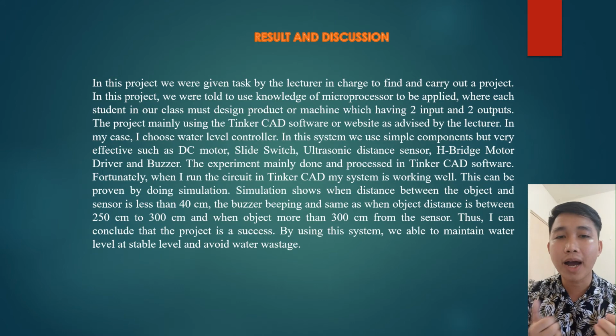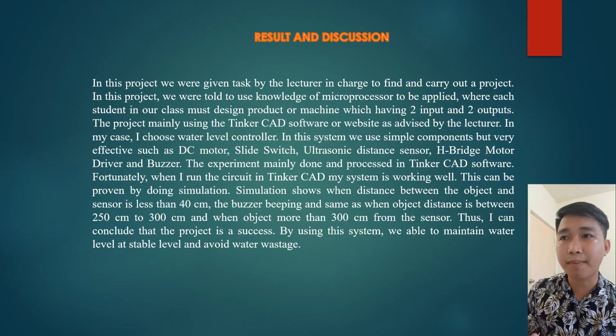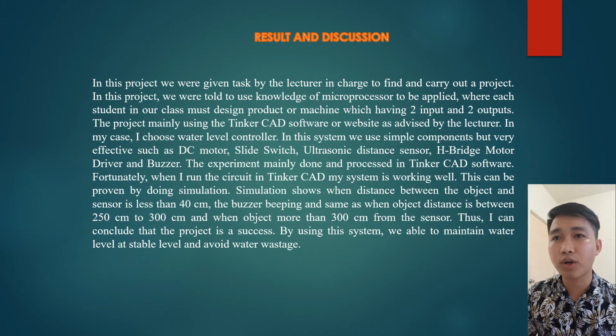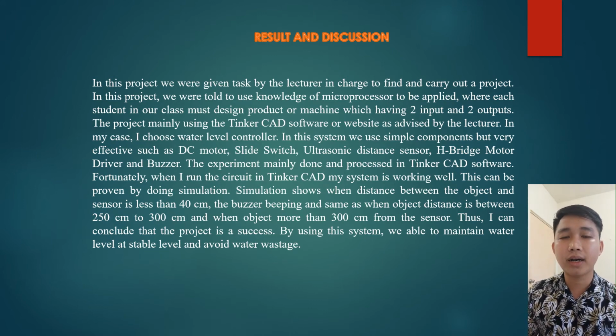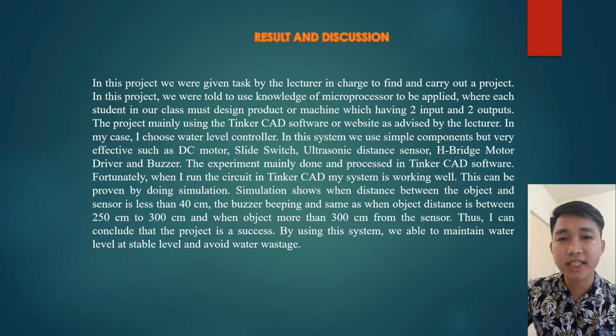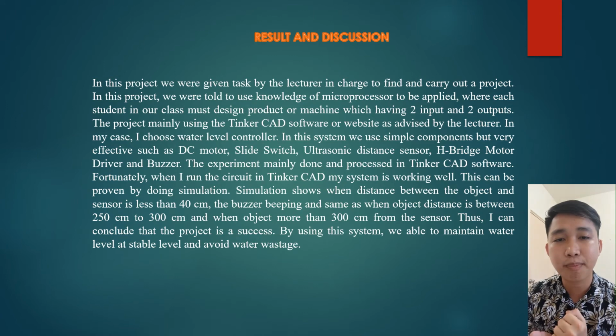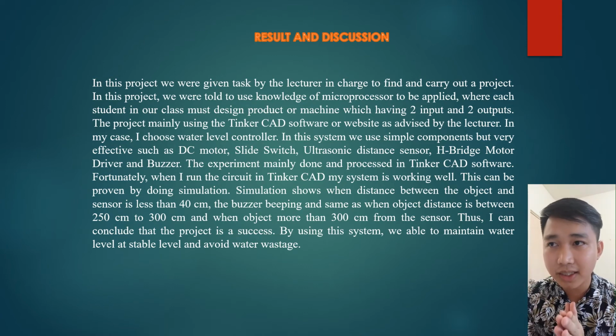My project is a success because when I run the project, the simulation runs well as I coded in Tinkercad. For example, when the water level is more than 300, the DC motor in the system will automatically stop, and that is the proof that my system is a success.